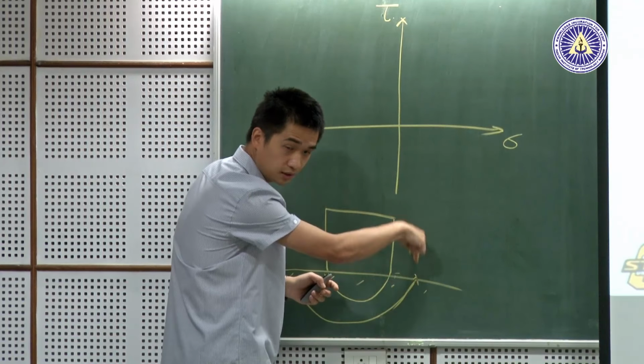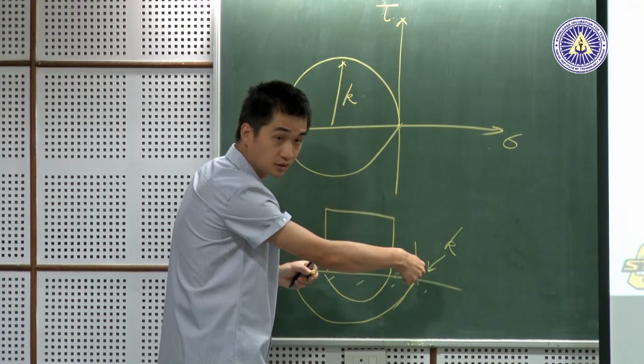Okay, then this stress Mohr circle always has this circle of flow strength k. Then if we analyze the point, this orientation is located at this point, but when it starts to rotate spatially, at the same point we see the stress distribution along different orientations.